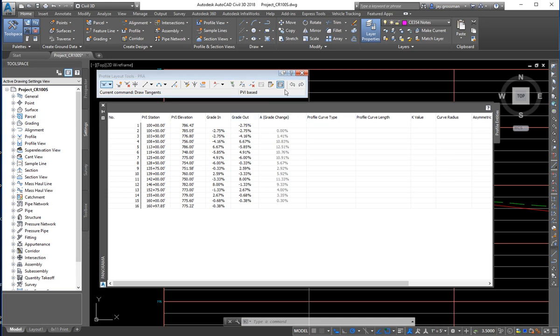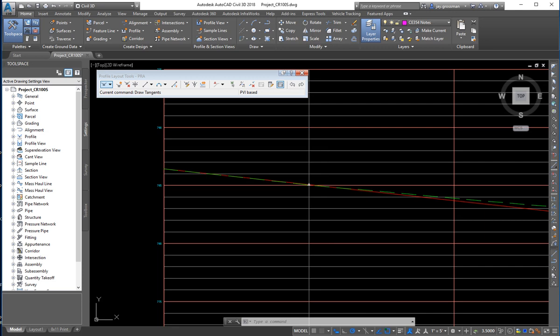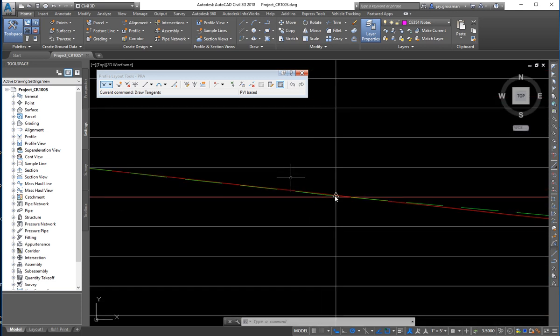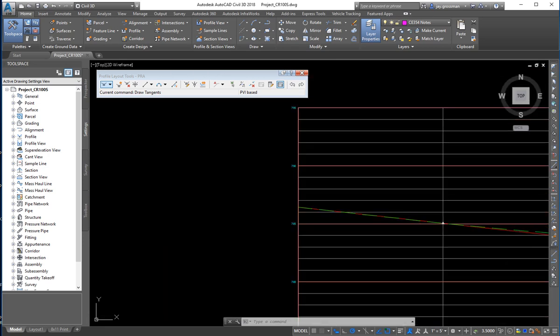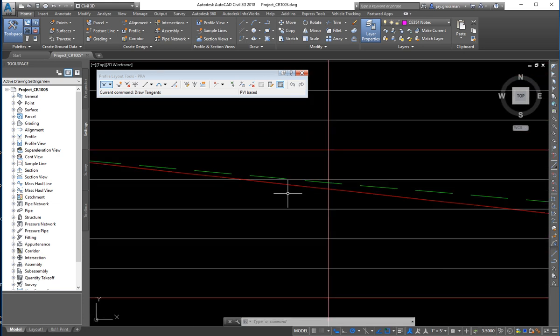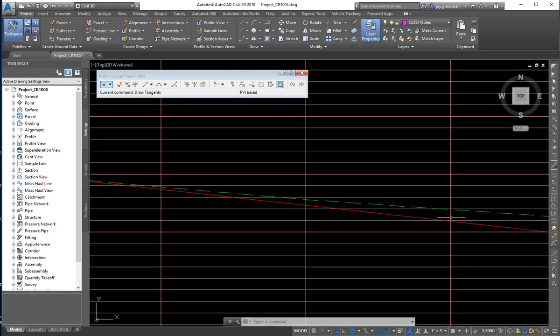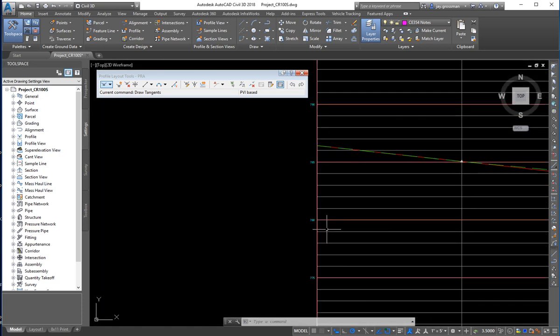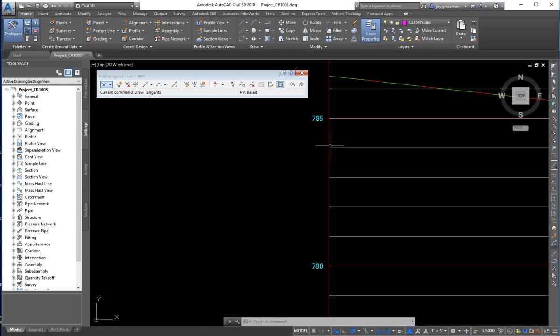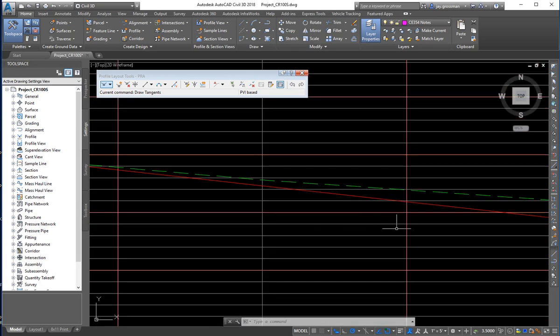We could eventually then get rid of that. Move this to the side. You can't see it now, but so I don't lose it. Now you can see we come through this PVI point. There's no need for this here now because we're continuing that grade on down as we come this direction. You can see we're continuing. Well, it's getting kind of where this is each of these lines. I think it's a foot. Let's check. Yep, 1 foot each for each line.